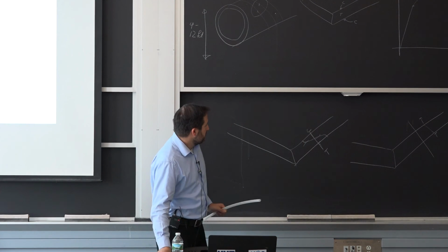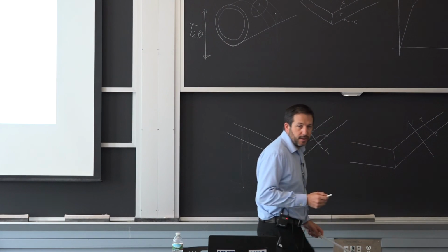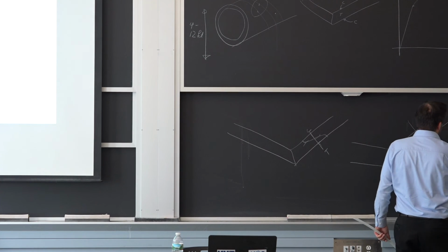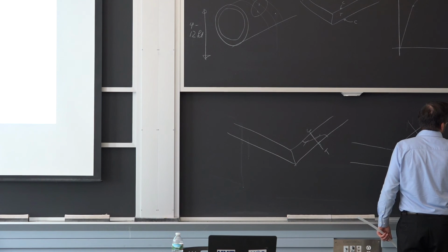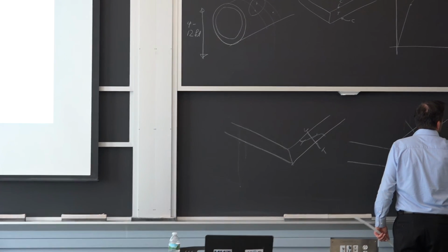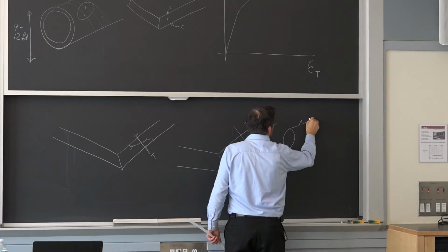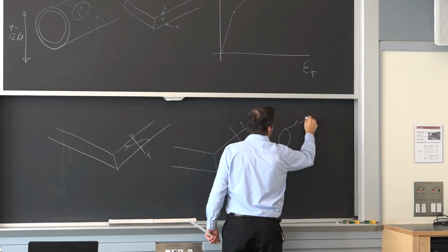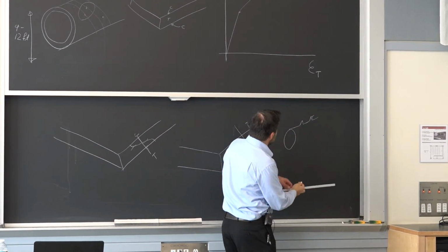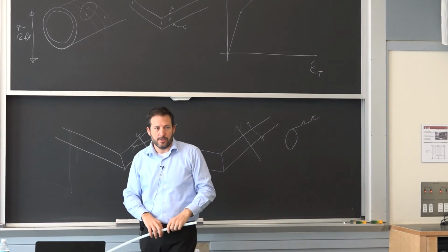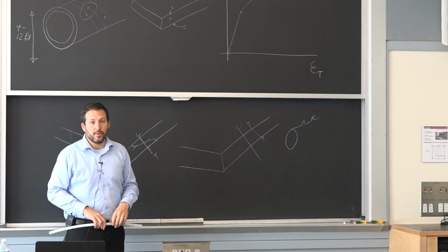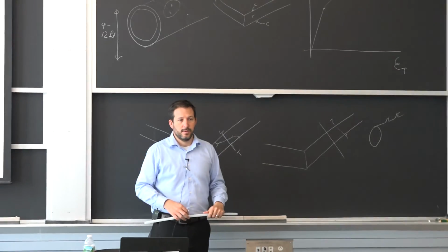So there's a characteristic on this one that allows it to work: there are barbs, and we don't see them, but let's say you have the fitting. On the profile, there's a little raised portion, like a teat, that the plastic engages over. So that's on the fitting itself. When you sit on top of this, it creates traction so it's not going to pull out in service.